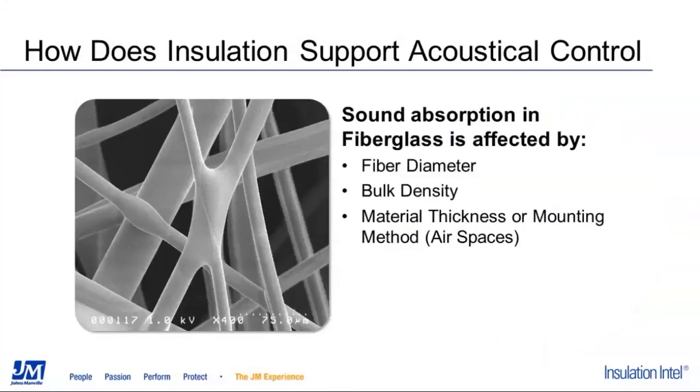How does insulation help with acoustic control? Well, very much in the same ways that it helps in thermal performance. If you're thinking about how a wave could be transmitted through a piece of insulation, it can move through the solid or it can move through the air within fiberglass. So those randomly oriented fibers provide a tortuous path.